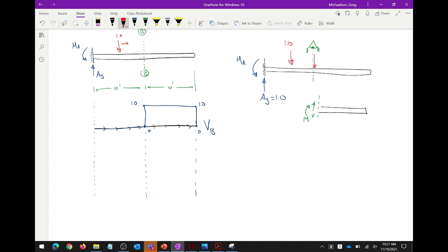And I put that load right there. What happens to V? It jumps to 1, right? And that happens. Now, what is V if 1 is here, or here, or here, or here, or here? What's V? 1. So we go from 0 to 1. That's your influence line for the shear at that point. Does that make sense? That is how you draw the influence line.